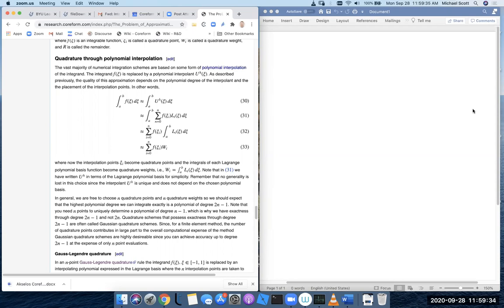So you'll see this. If you take a bunch of finite elements and connect them together, and then you try to approximate something that looks like that, no matter how many elements you use, you're going to get these overshoots and undershoots. C0 is worse than smooth, but you'll still get them.